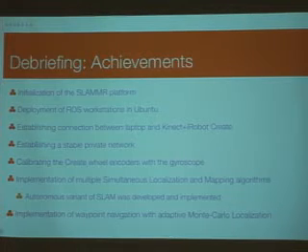We also implemented two different types of SLAM, and one of the SLAM, the grid mapping, was implemented in such a way that it's autonomous. So we basically run it, and it runs automatically and will map out the whole room. And afterwards, we implemented waypoint navigation with AMCL localization.